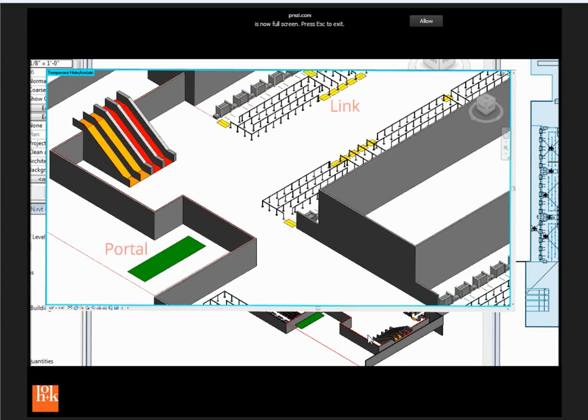They need links. They need to be able to get across floors, understand how to get through doors, and get through turnstiles. There's escalators. IFC, just so you know, does support the transport element. It does support escalators, elevators, everything, but Revit obviously does not, right? There's no good category for vertical transportation at all. But something's been sorely lacking for a long time, and we're still to address it.